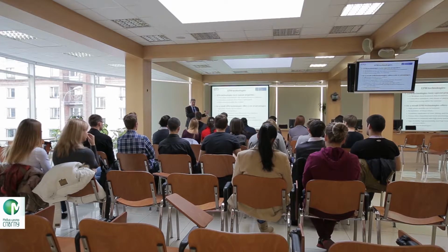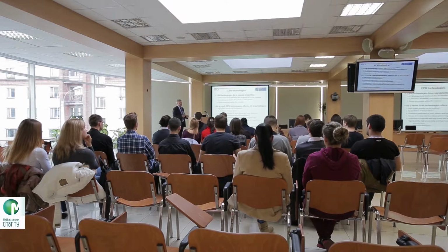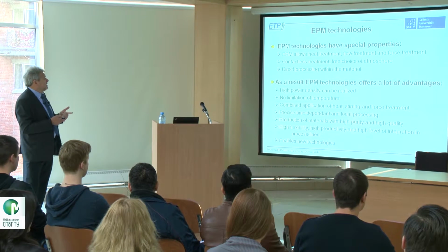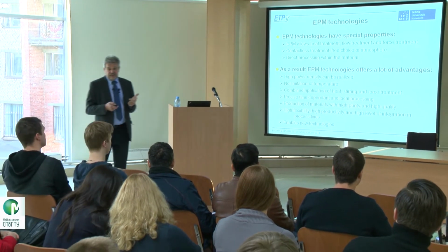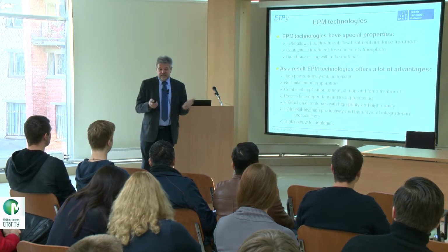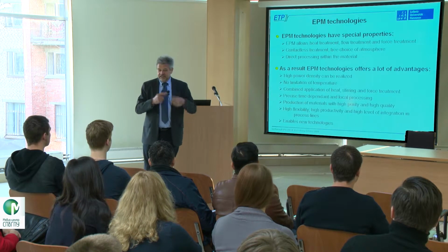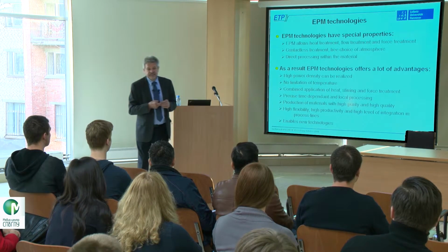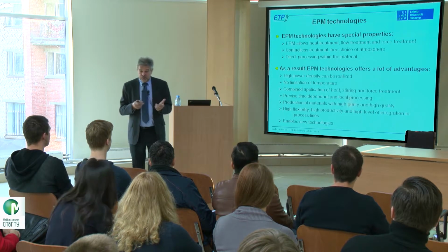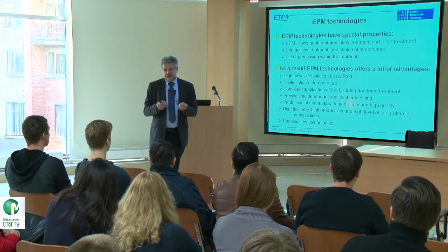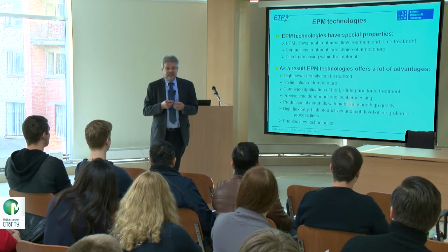EPM, as I call it, electromagnetic processing of materials technologies, have special properties. They allow heat treatment, melt flow treatment, and force treatment. Electromagnetic fields, described by Maxwell's equations, can generate heat if you have currents in the material, which we call Joule heat, and on the other hand, they can generate forces. The main part are Lorentz forces, and these forces can drive liquid melts, for example.